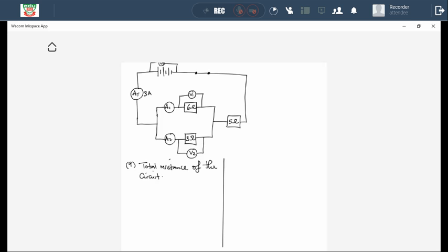But here is the method. Total resistance RT is going to be equivalent to the parallel resistance RP plus that other resistor which is in series, which we can call RS. So the first thing we need to do when we have such a circuit, Grade 10, is come up with our parallel resistance first, using the previous method that I showed you in our previous presentation. Then when you get that RP plus the one that is in series, you get your RT. Is that okay? So I need to determine my RP first so that I can add it to RS, and then I get my RT.